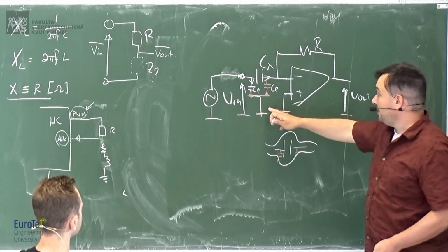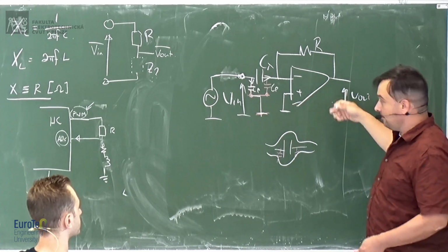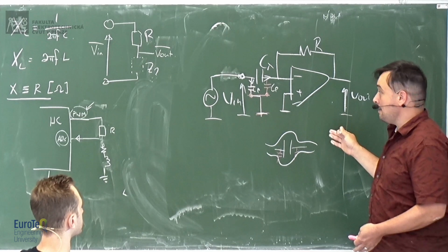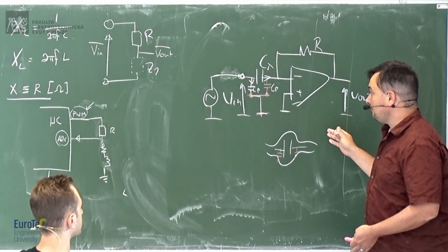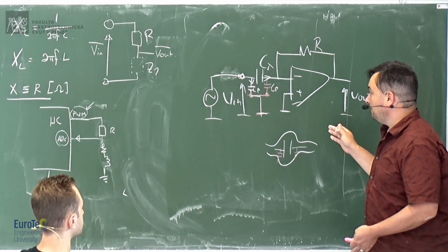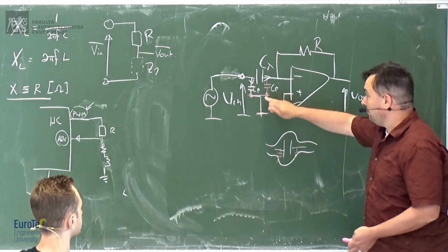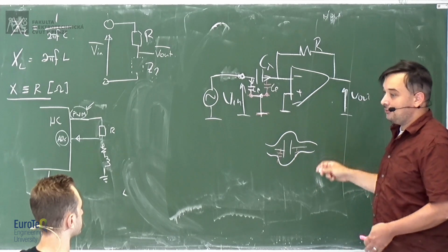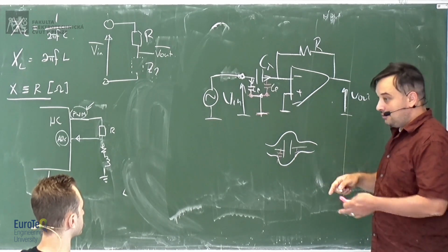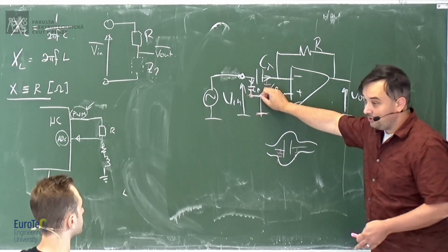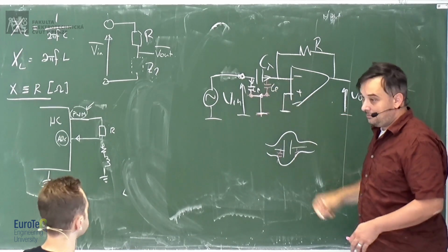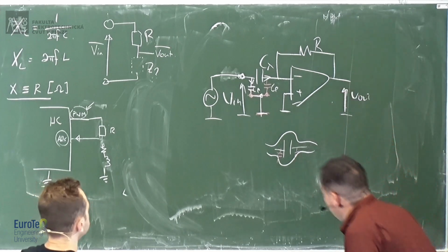So now, be careful, because if you use one of those chips, like the one that I've shown before from Analog Devices, you might want to remember this fact so that you know that maybe you can find the ground in the chip, and you connect the ground to this point to avoid this measurement of the parasitic capacitance, okay?